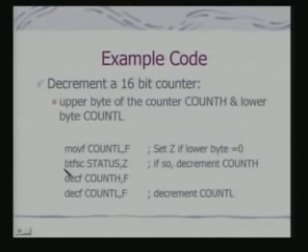Fine. Now, the interesting feature is, if an interrupt occurs while this code is in execution, what can happen? Your decrement may not take place correctly, because your counter is not getting decremented by an atomic operation. Is this clear? Because there are 2 bytes and they have to be decremented. So, if you want to ensure an atomic decrement operation on this counter, you need to protect this code. That means you need to disable the interrupt from occurring.